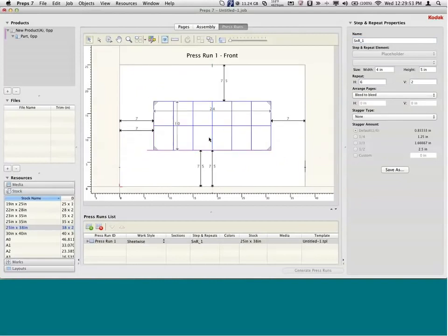So a cell gives us a whole new capability. There is no assignment of pages here. If I'm in a die-making environment, maybe I know I need to have N across and Y tall of how many of those products on the sheet. I have this step and repeat capability. It also allows me to take advantage of how I'm going to work with my pages: trim to trim, bleed to bleed, allow a certain gutter, and the gutters allow me a horizontal or vertical difference. And then distances, so what could be the gaps between that? Okay.